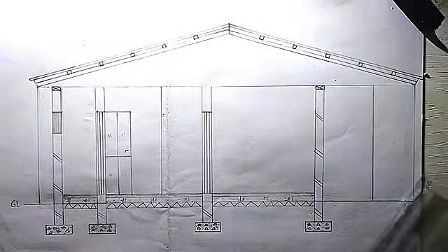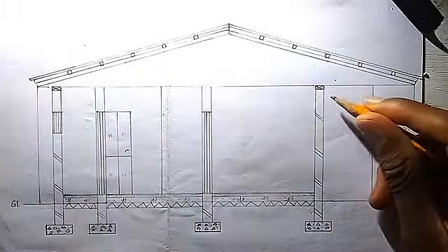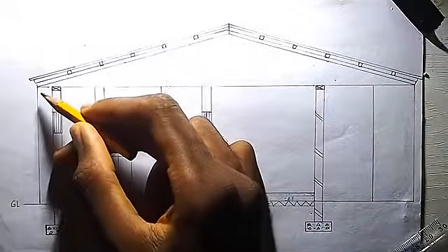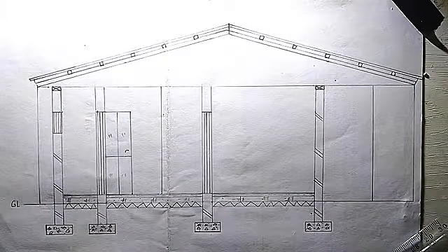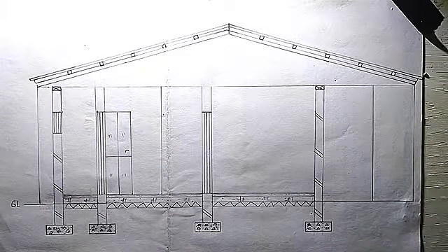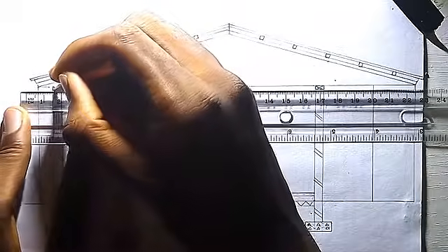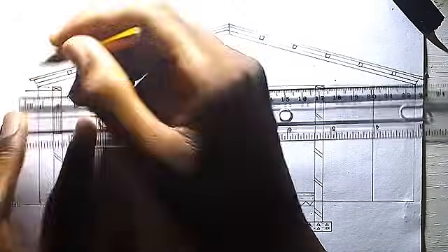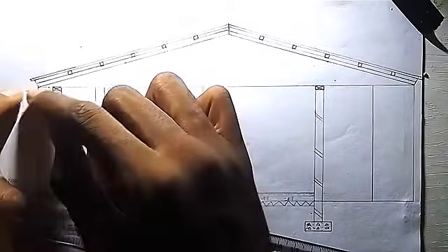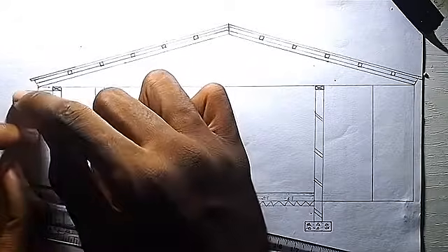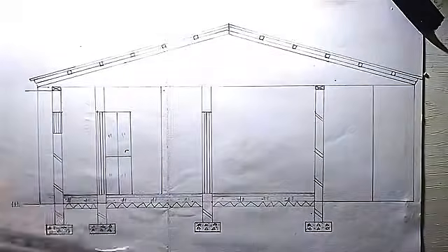And you have to cross it to indicate it's the wall plate. So just mark an X to indicate it's the wall plate. Then from the wall plate, we have to measure out our eaves projection. This projection, 750 divided by 50, is giving us 15, which is 1.5 cm. So from the wall plate, we mark 1.5 cm to get our eaves projection, which is here. So this roofing sheet will have to extend downwards rather. You do not stop, you have to extend downwards, then the eaves projection has to join upwards with the roofing sheet. So we'll take note of that.